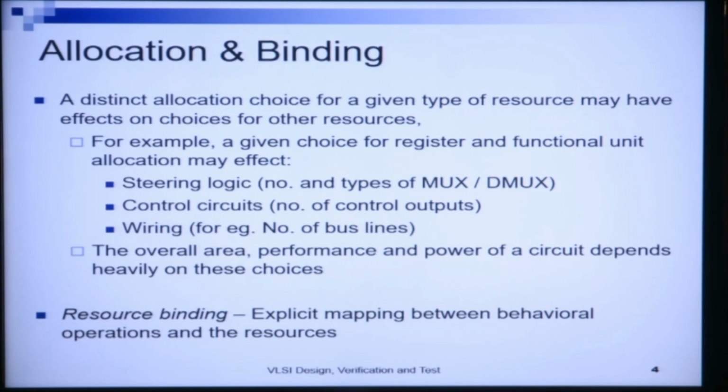So, a choice of which variables you have put on which registers, and which operations you have mapped to which functional units, will decide the number of muxes and the types of muxes, a 4:1 mux or an 8:1 mux.